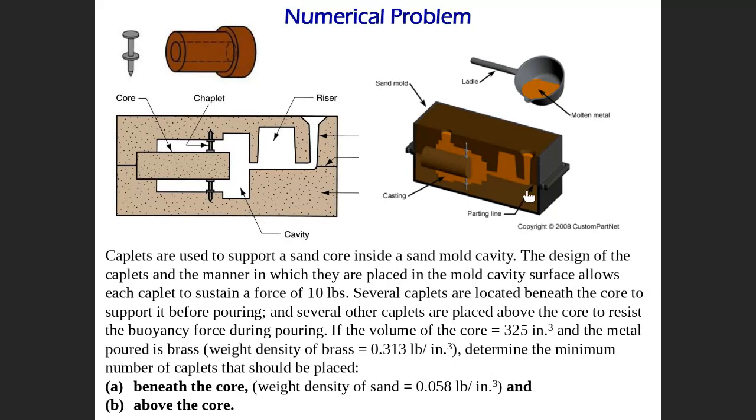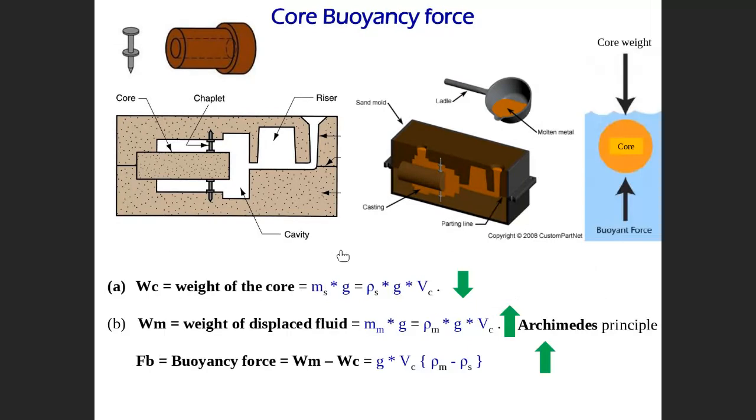I have a question about the weight of the displacement fluid on this slide. Since it's weight, why do we consider it up, not down? We usually consider the weight direction downward, not up. Exactly. But this is liquid fluid. They consider the liquid pushing up with a force equal to the weight of the displaced fluid, because this fluid is supposed to be filling this area.